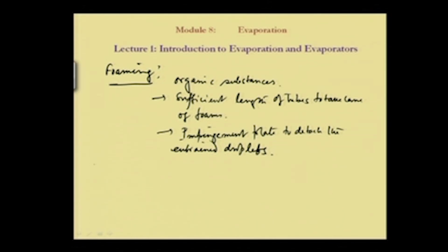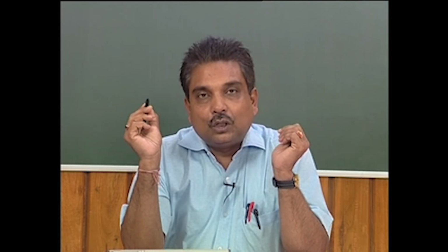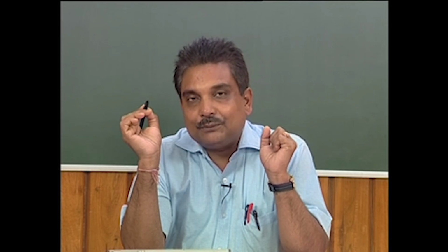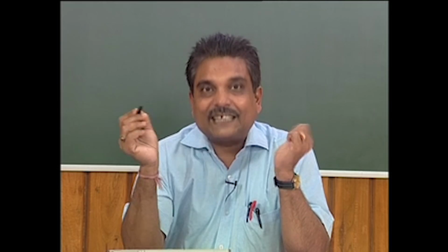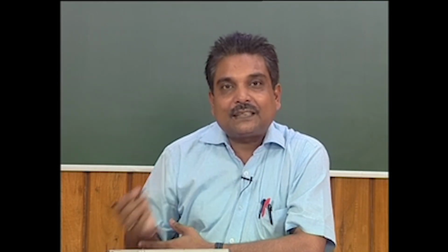And then temperature sensitivity. As we know, temperature sensitivity is very important, because heating is there. Evaporation means it is heating and the liquid gets boiled up. So, if the liquid material is highly temperature sensitive, then we should be pretty careful, because if we give long exposure at higher temperature, then there can be damage to the materials.